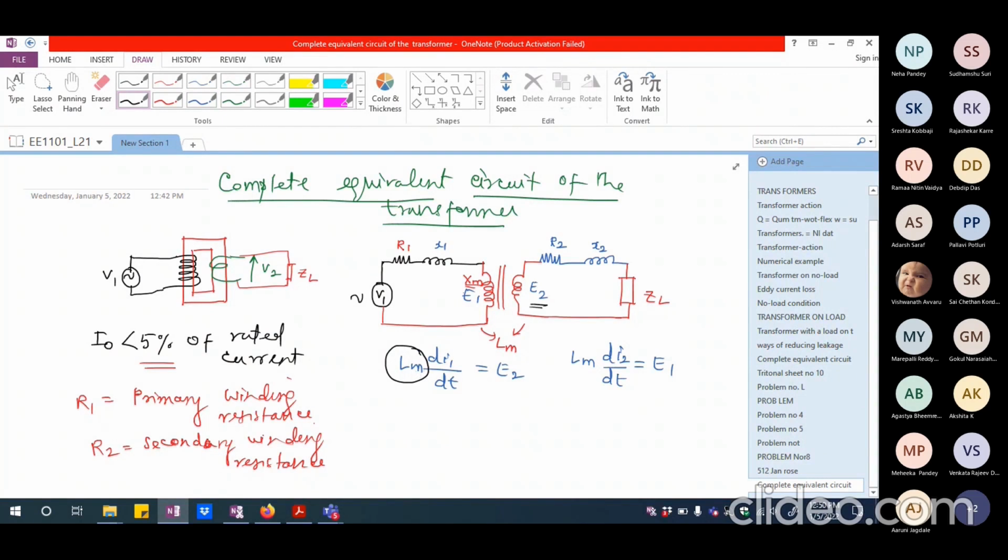There is no secondary current at all. And the primary induced EMF is because of its own flux. There is nothing coming from the secondary. Okay. So I should say that this is causing really the mutual induction between the primary and secondary. So what I should show here is some Xm value, which is actually the root cause for the transformer action itself, which is common to both primary and secondary.